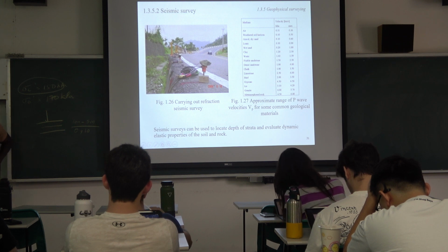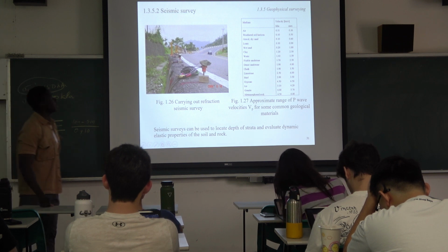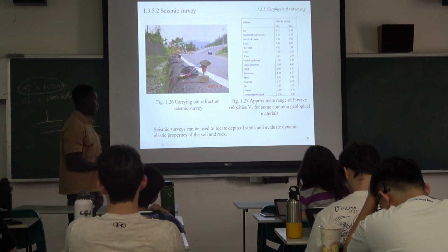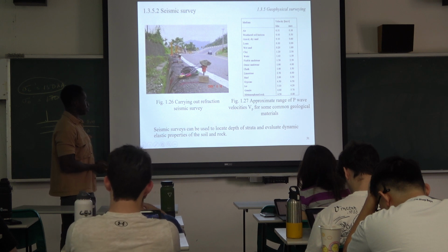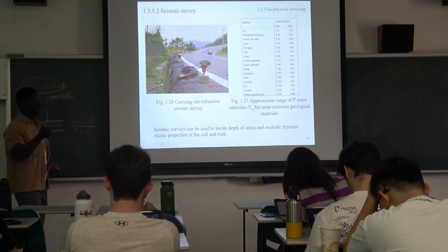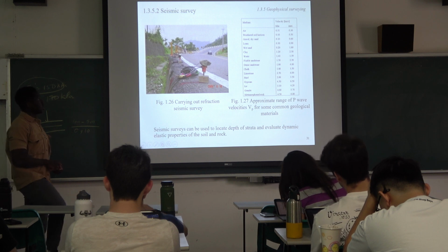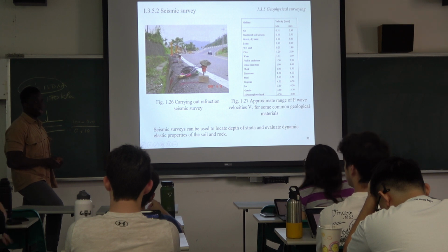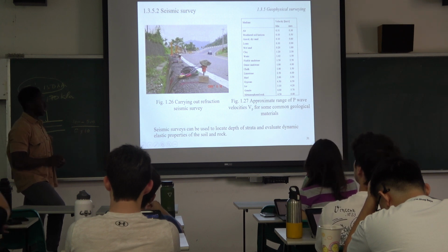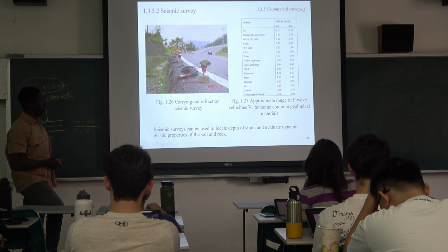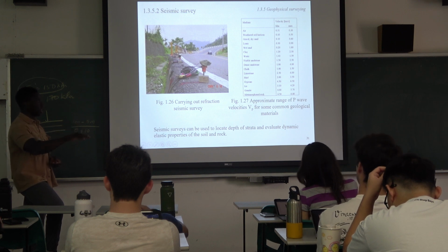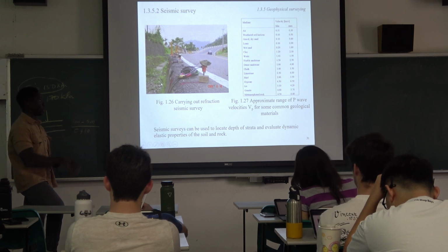Okay, and the next one is the seismic surveys for earthquake problems. The seismic surveys can be used to locate the depth of strata and evaluate dynamic elastic properties of soils and rocks. If you are trying to do dynamic analysis, in some places you probably don't have to worry about this if you don't have earthquakes. But in places like Taiwan, they will typically do this a lot. They will do the seismic surveys to try to understand the soil condition and the resistance or the layers and the various strata of the soil properties and the rocks.